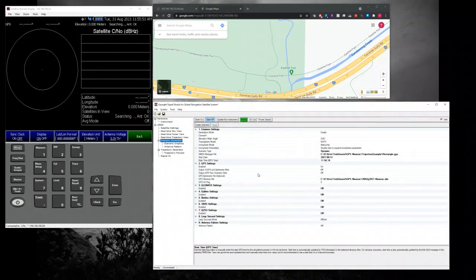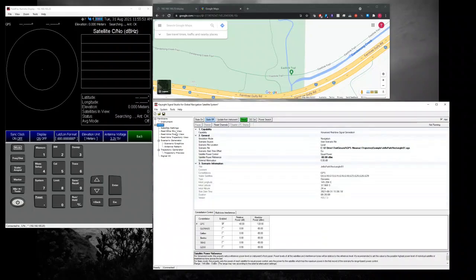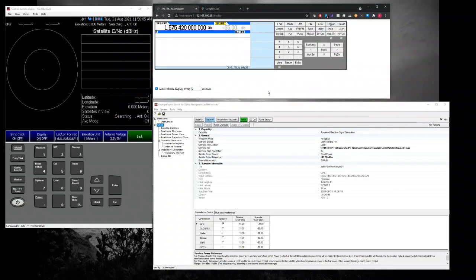Okay, replace it, and then we are ready to go. I noticed that for this dynamic we need to have higher power. Let's say we put it at 65. And again, you can change this power after you've done it. Once you're happy with that, we just go to state on, and it should download there.